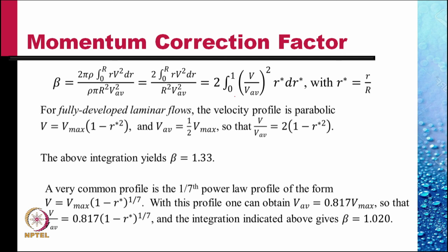So, if the flow at the inlet or the outlet or at both locations is turbulent, as it is more likely to be since most economical flows are turbulent, we may not apply the momentum correction factor because this will result in an improvement only by 2%, not significant.